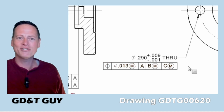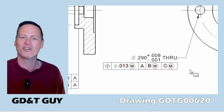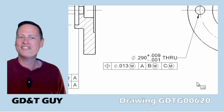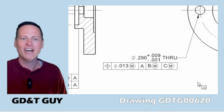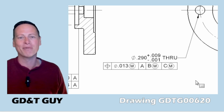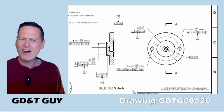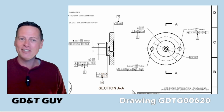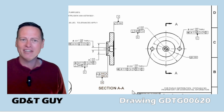Now let's all pause to roll our eyes at this second hole call out. All right, this is the idea that there has to be a tertiary datum feature, which parenthetically, again, the standard says explicitly in this case that we don't need. Okay, so far, is this wrong? Not necessarily. This is legit GD&T in the sense that it has a meaning and recognizable interpretation.